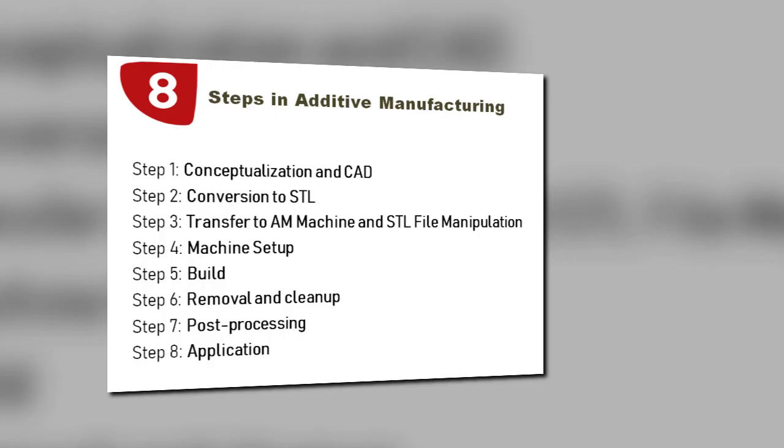Moving on, we look into the different steps involved in the additive manufacturing process. Additive manufacturing involves a number of steps that move from virtual CAD description to the physical resultant part. Different products will involve additive manufacturing in different ways and to different degrees. Small, relatively simple products may take only additive manufacturing for visualization models, while larger and more complex products with greater engineering content may involve additive manufacturing during numerous stages and iterations throughout the development process.